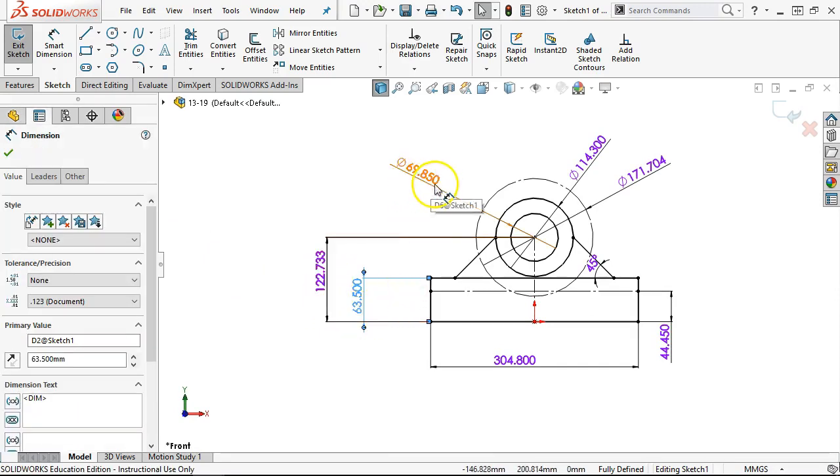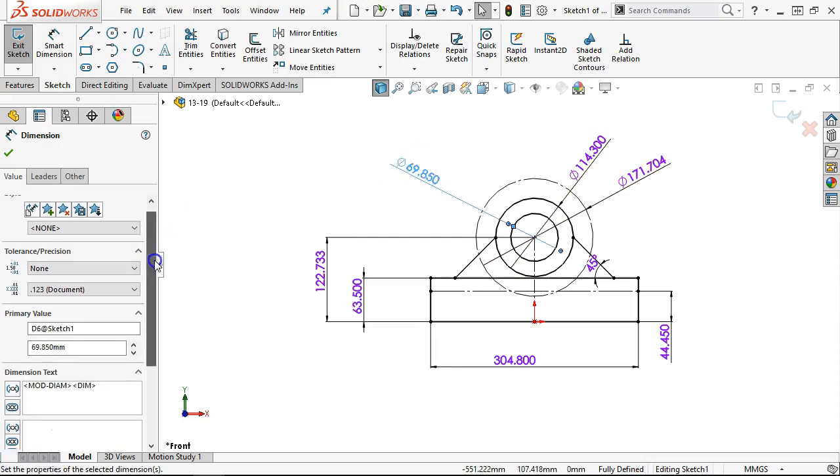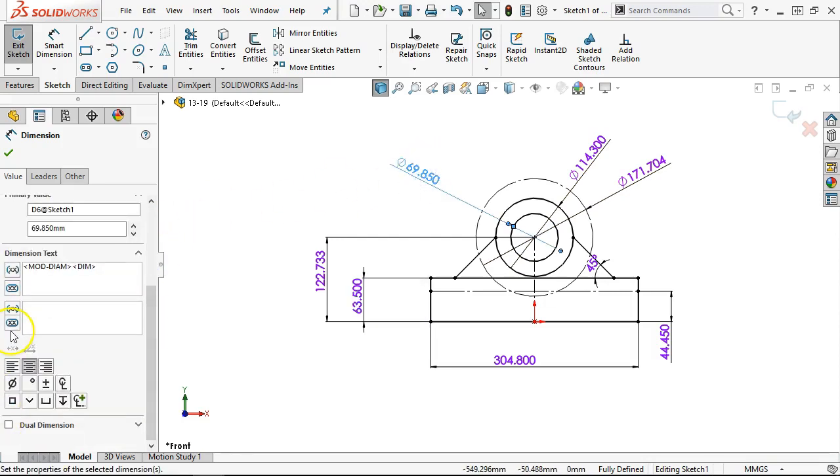Most of these are not too far. You get out 2 or 3 decimal places in metric. You really, 4 tenths, half a thou on all of these is going to be a little on the extreme side. So the 114.3 I could live with. The through bore, I'd have to consult the tube manufacturing. If that's going to stay an inch number, then this would be where I'd want to consider using the dual dimensions for that item.